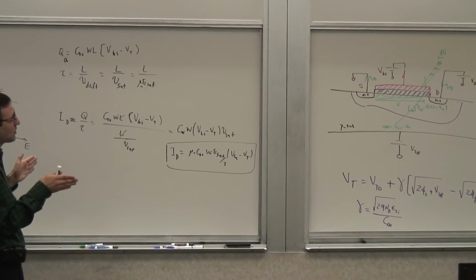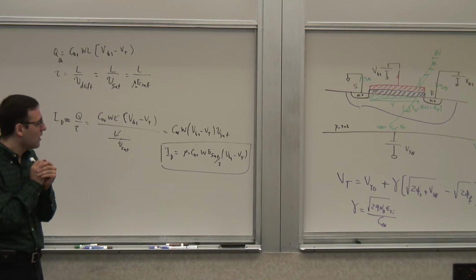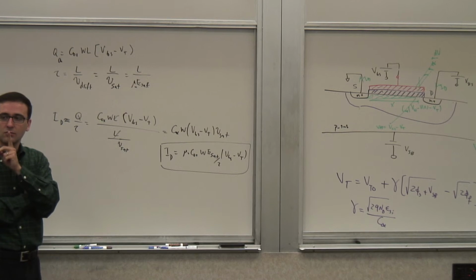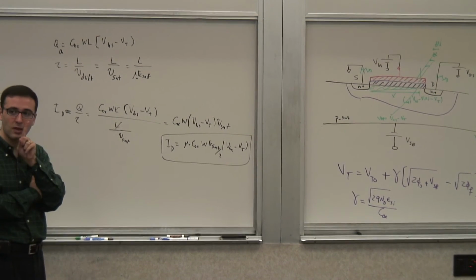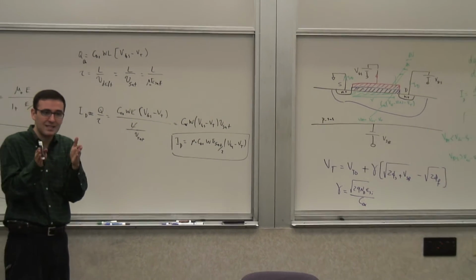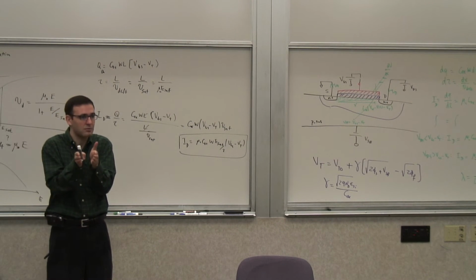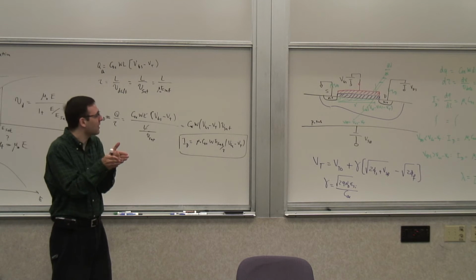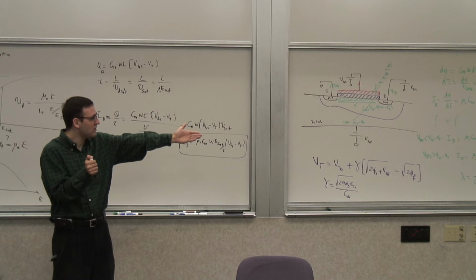So when I shrank my L, the length of the channel, before, I gained because of two things. My speed went up because of two effects. One is that my capacitance became smaller, because L became smaller, right? The area of the gate became smaller. And the other one was that I got more current, which was more bang for my buck, for a given change in V_GS.